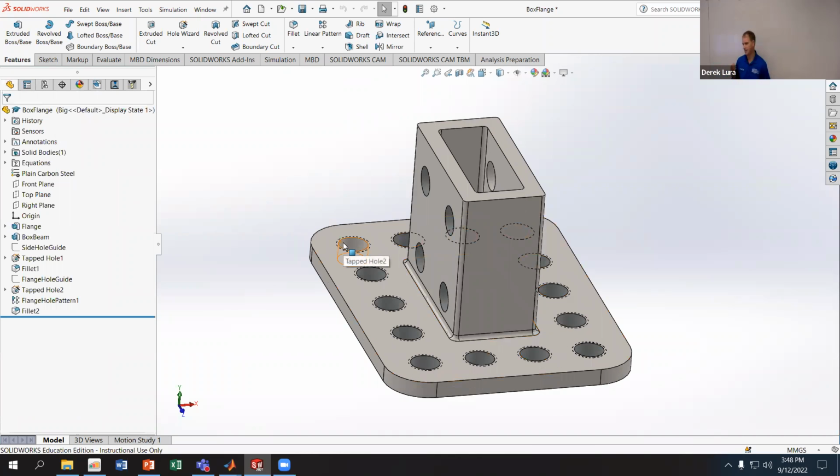So pretty straightforward. You do want to be careful when you're doing this, especially on a CSWP, that when you change things, you're not breaking stuff. Applying changes to just the current configuration is the most conservative change. Applying it to all configurations is the most likely to cause issues because you're changing a bunch of things all at once, right? So when in doubt, I would suggest you only apply the change to either selected configurations, where you're doing it for only the specific ones, or to the current configuration, where you're less likely to break things.